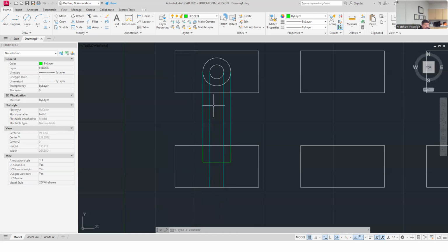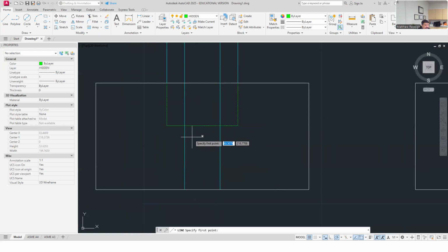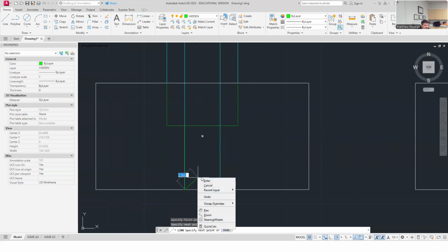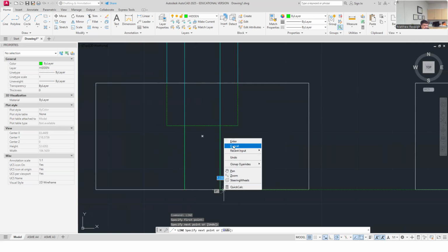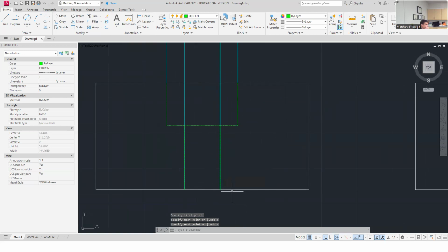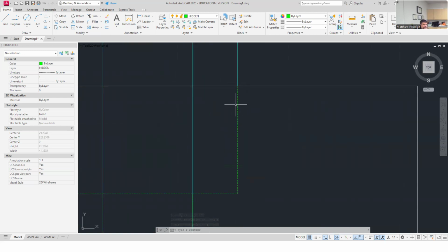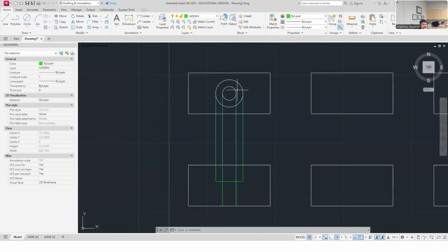So we have unfinished stuff going on here. We don't really know what I'm attaching to, but this would come down like this. So I have my hidden line on still, and this is the inner bore that goes down. And then I would say enter. And the nature of hidden lines, they are actually visible features, right? Like that is that drilled hole, two different diameters, one all the way through, one only 12 millimeters deep.